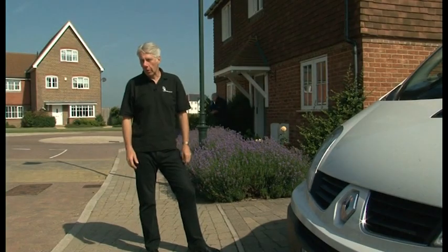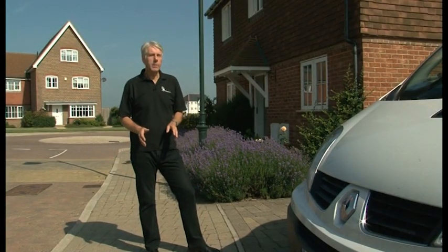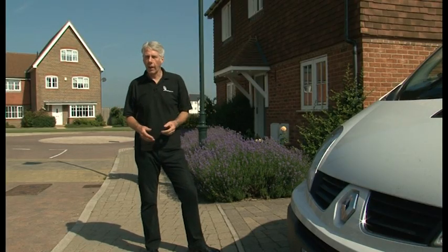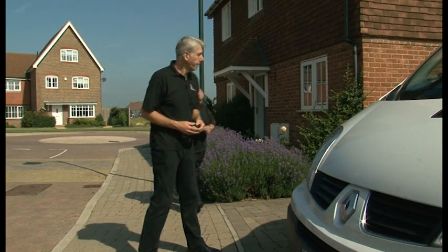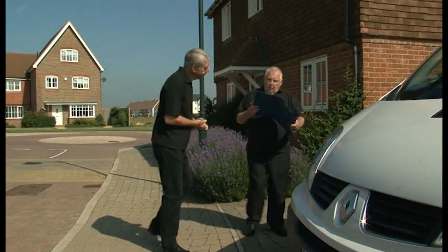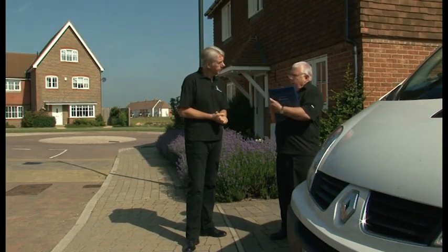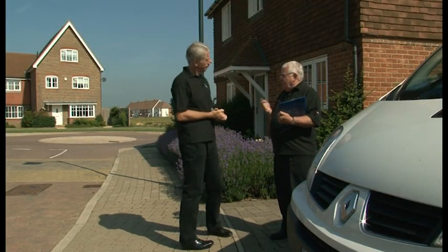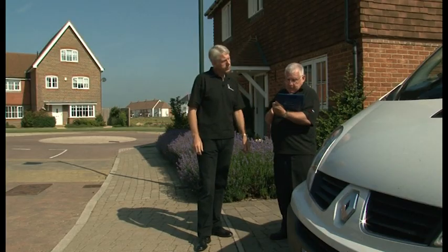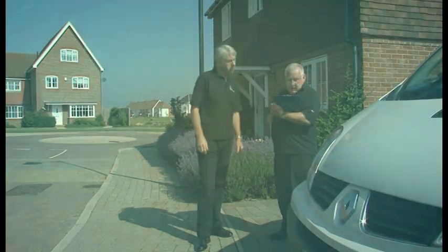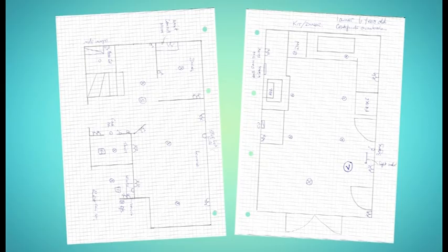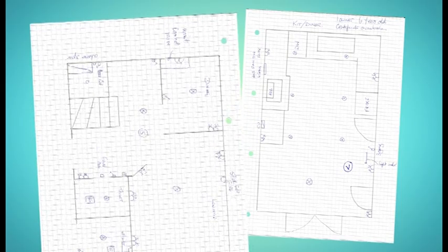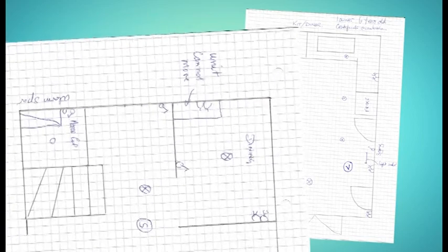Tony will also explain to the occupier that at times the power will need to be switched off, which will mean that clocks and the like will need resetting at the end of the day. So how's it looking, Tony? Well, this property has only had one occupier and is about 6 years old. So the installation was installed when the 16th edition was current. We do have an electrical installation certificate, which is handy, and I've drawn diagrams for each floor. I've done a separate one for the kitchen and a separate one for the garage, marking all the accessory points, including those which are inaccessible. And there are a couple actually we can't get at.